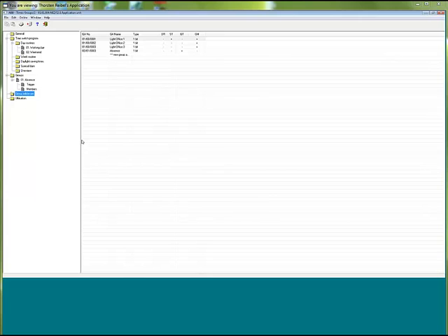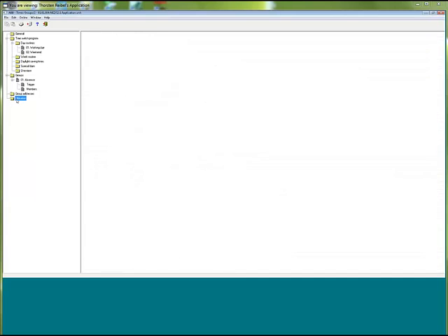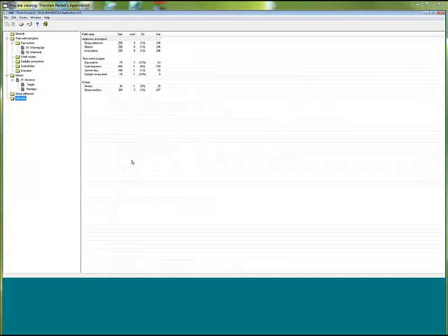You have an overview of all used group addresses, in which day routine, in which switching time it is active here. Is it in any group? Is it a group member or is it group trigger? You see here, good overview of the group addresses. And finally, the utilization means what out of the possible time functions and groupings you have used already. Remember, 800 switching times possible. Only one is used at the moment. Only one group out of 30. In total, we have 300 group members.